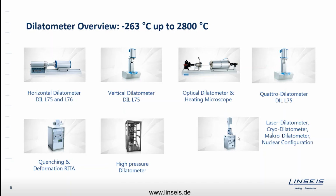which is the laser dilatometers for ultra high precision. It's a push rod with a laser within the push rod that measures the exact distance between measurement system and sample using interferometers, obtaining the highest possible resolution. We have cryodilatometers or cryodilatometer series where we use liquid helium. I will show you also. So using the liquid helium, reach temperatures up to 10 Kelvin.